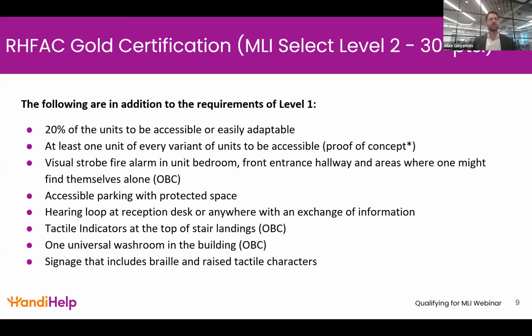Somebody asked, please give an example of a 1200 millimeter choke point. So if you have an L style kitchen, if you can picture an L when you walk in through the front door, and the L sort of sticks out perpendicular to the hallway going into the living room, as long as that counter, that L, is not wider than 600 millimeters, then that L can encroach on the path of travel from the front door to the living room.